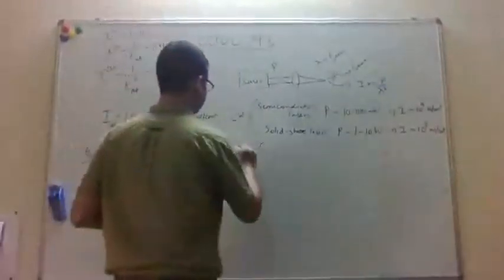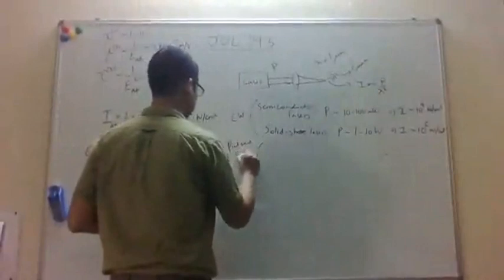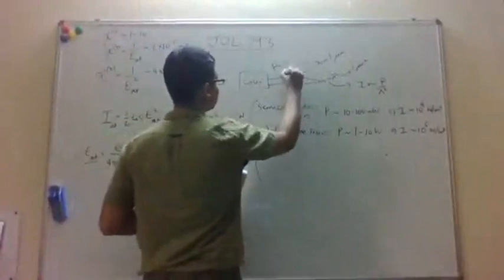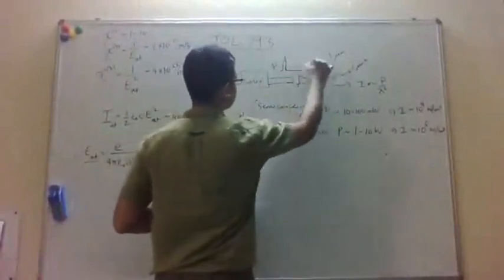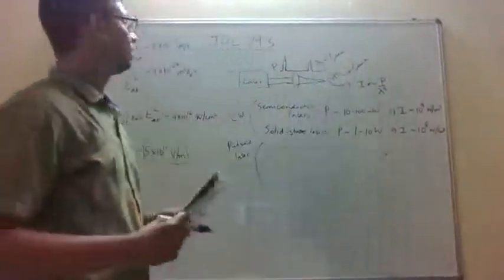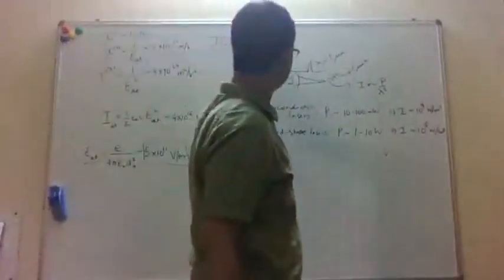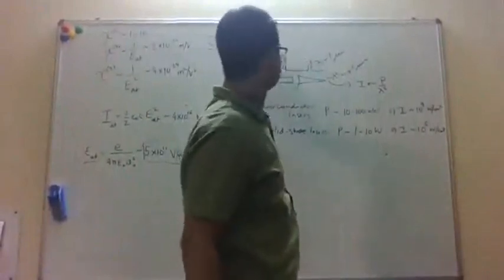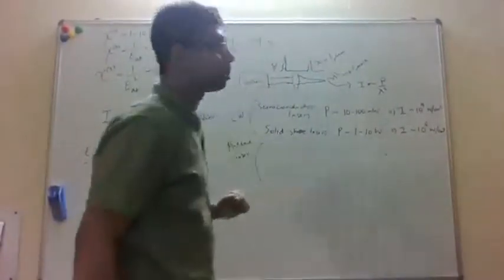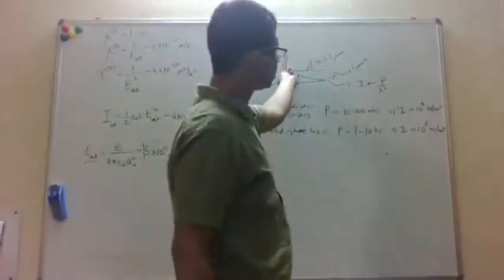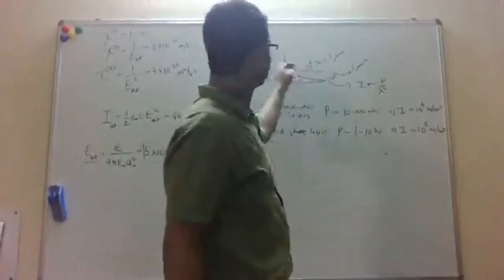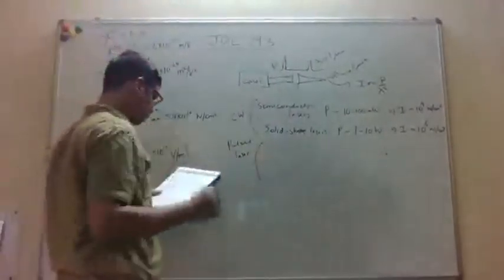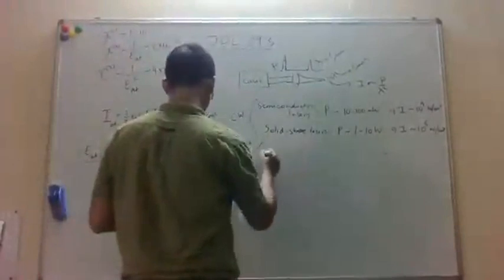Right? But then you can have pulse lasers, where the output is sort of pulsed. So you get nothing for a long time and then a huge spike at periodic intervals. Okay? And with a pulse laser, basically what you're doing is integrating the power over this entire time period and then dumping it in this very short time. So you can imagine that if you have a very short pulse compared to the time period, then this power here can be really large. Okay? So with pulse lasers, you can get peak powers which are much larger.